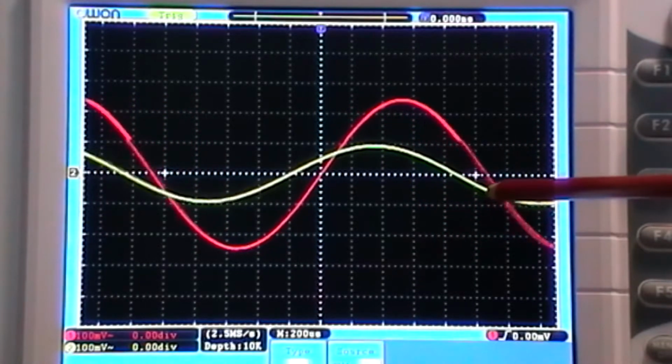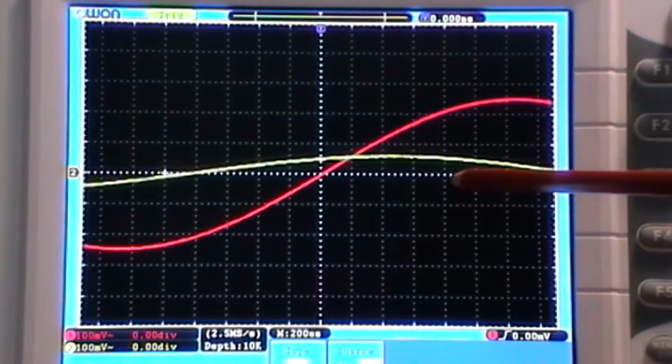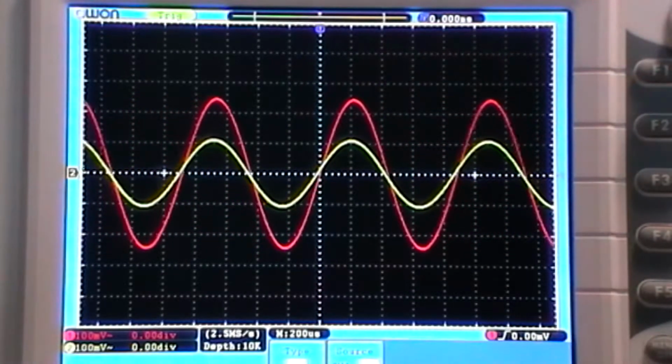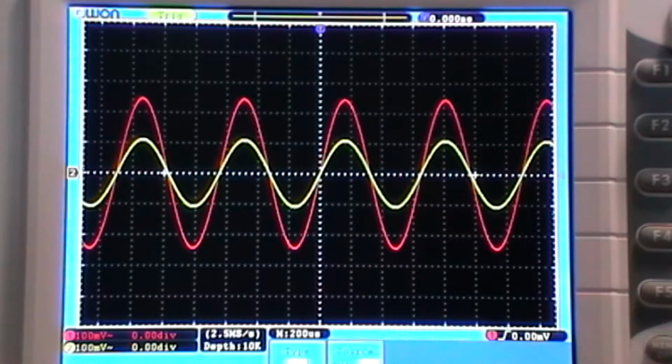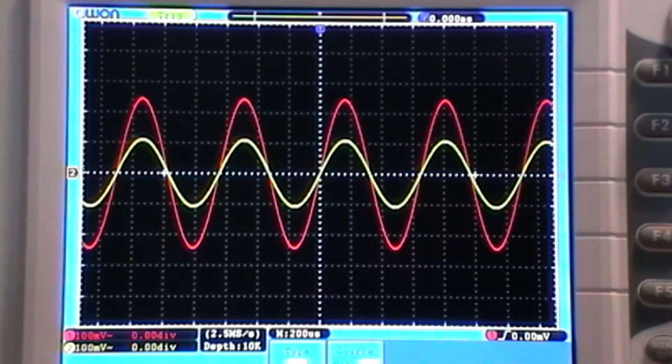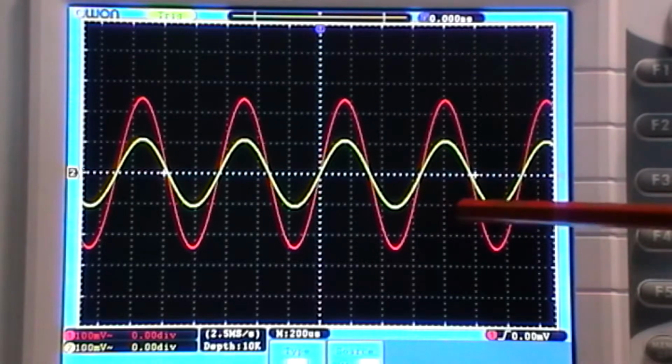I expect when we get right down to the bottom level, some attenuation there between 100 and 300 hertz, but it shouldn't be doing that, should it? It should stop that about there. It should be attenuating this properly, but it's not. So putting the filters in the right order does seem to be important. You seem to need the high pass filter and then the low pass filter, otherwise this thing doesn't work properly. So there you go, that's the band pass filter with a passive RC low pass and high pass filter put together. Very simple.